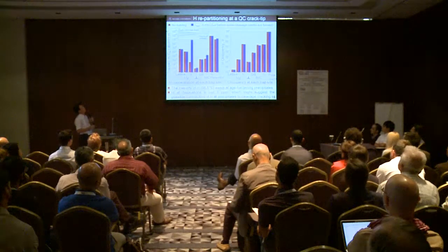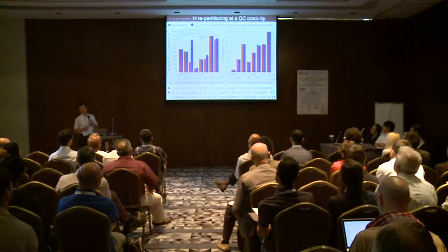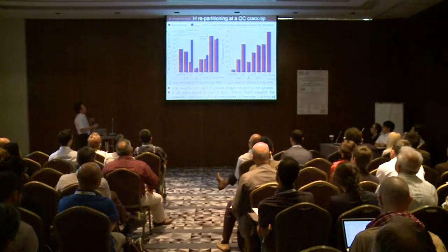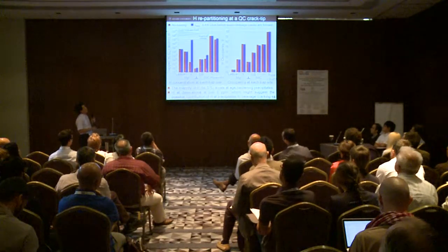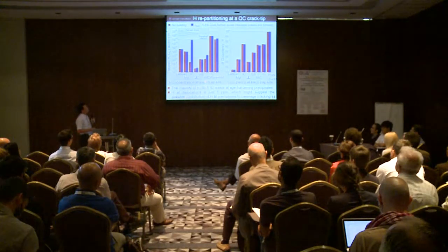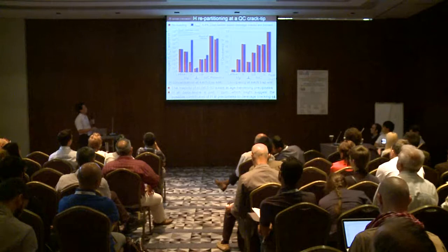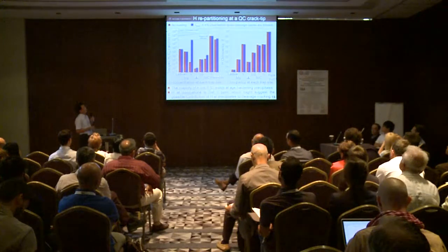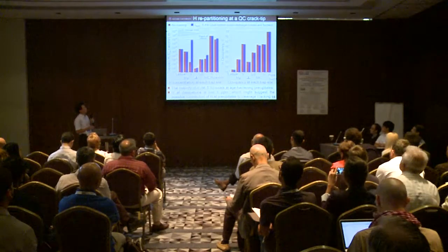And at a glance, you can see that hydrogen concentration drastically increases at vacancies. This is due to the drastic increase in vacancy concentration. And probably the highest hydrogen concentration is observed at precipitates. So roughly 2/3 of all the hydrogen exists at age hardening precipitates, and the remaining 1/3 are distributed to the other trap sites.